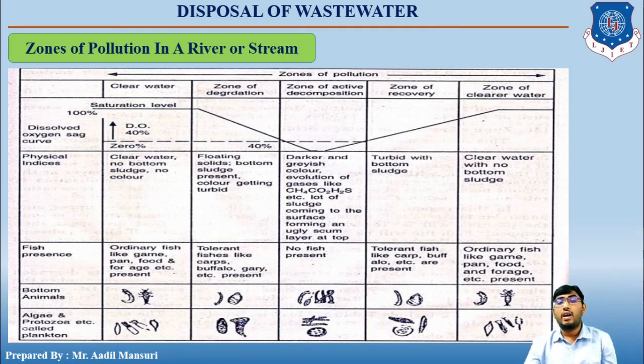It is approximately 7.6 milligram per liter of dissolved oxygen, whereas at 20 degrees centigrade it is 9.17 milligram per liter. So there is an increase in carbon dioxide content and oxygenation occurs, but it is at a slower rate than deoxygenation. These conditions are unfavorable to the development of aquatic animals, and as such, algae dies out, but certain type of fish may be present feeding on fresh organic matter.